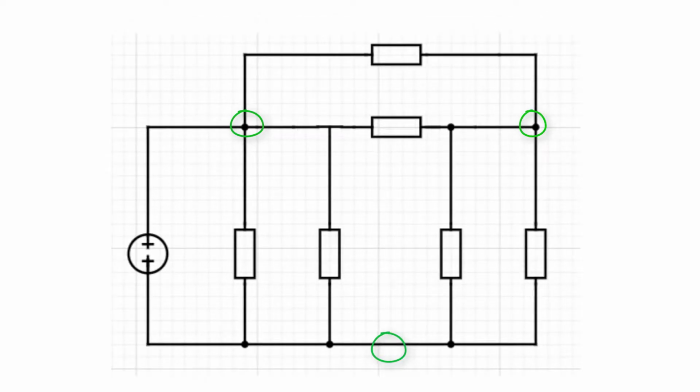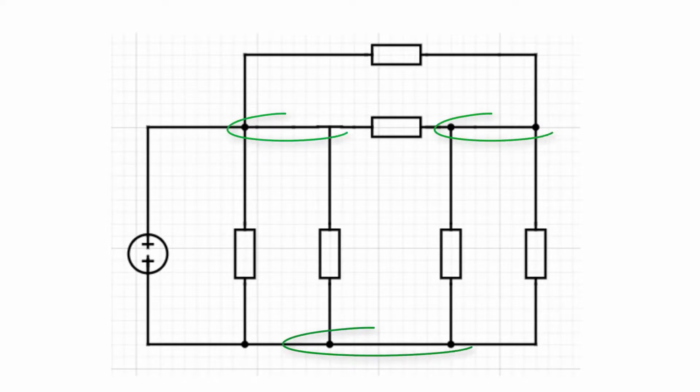Don't worry if this looks like a very different delta circuit than you saw before. You need to get used to understanding the idea of voltage references. The three connections of the delta Y are voltage reference connections. As long as the three voltage reference points of the final configuration match the three original voltage reference points, then you have an equivalent circuit.